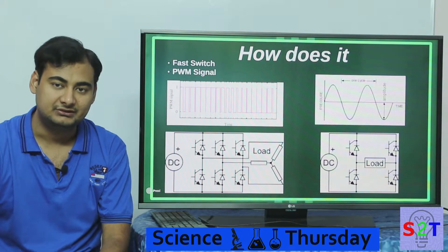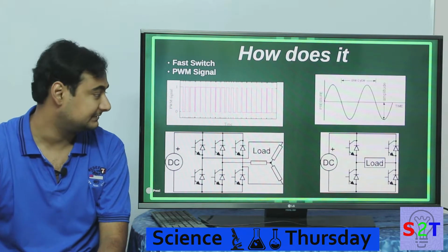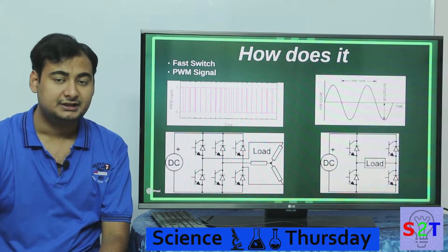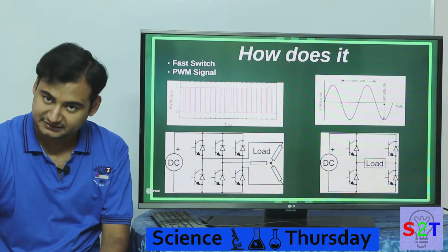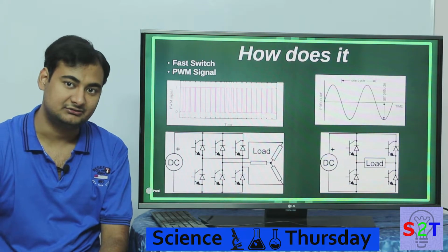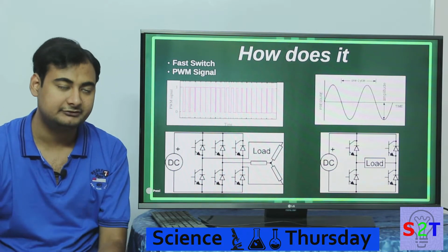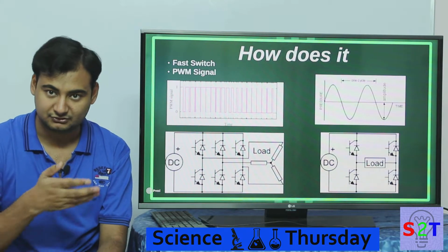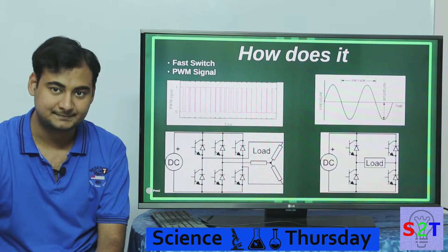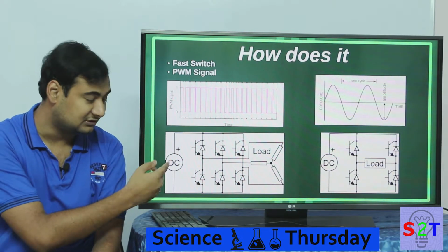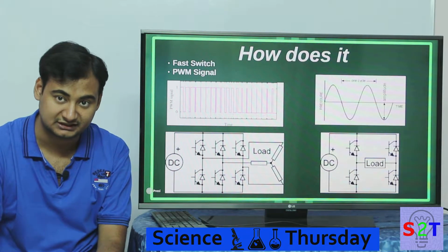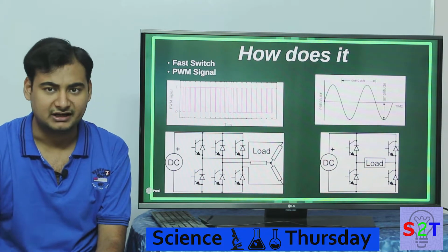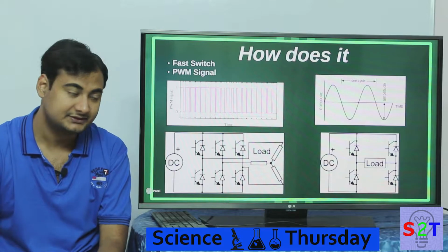This is how we ended up creating a sine wave inverter. What we did is, all these switches, we are turning them on and off much more than is needed. In older designs, which you can call square wave, what we used to do is only turn on and off 60 times a second, to make 60 hertz mains power. However, because of the advance of fast silicon electronics or solid state IGBTs, we can do that thousands of times a second. So what does that allow us?